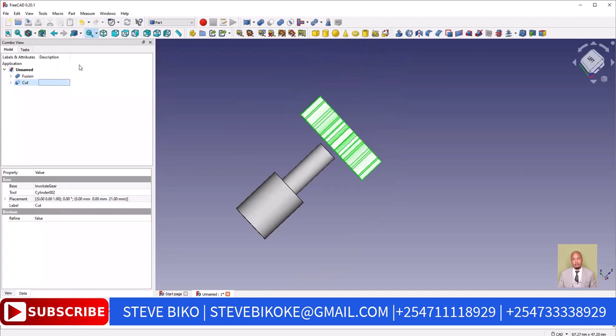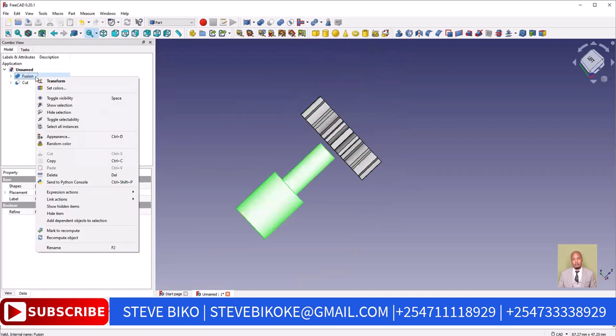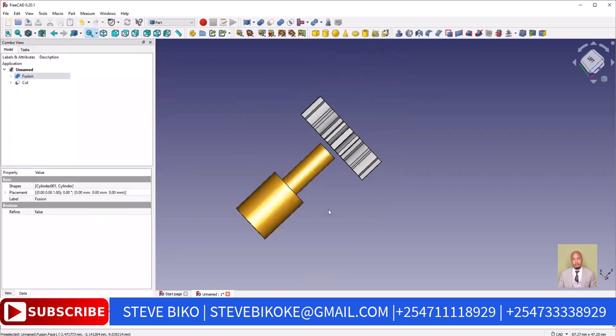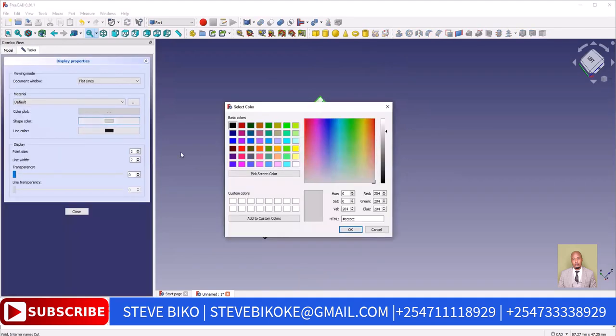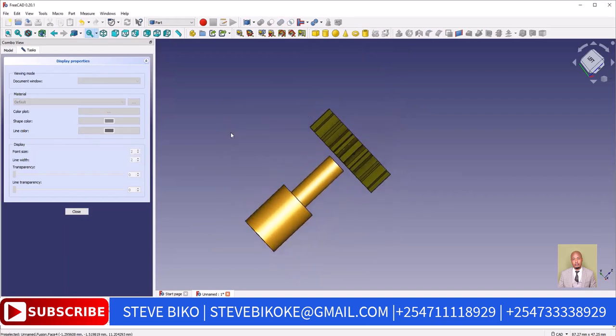Then now we can give them some nice color. So we start with the axle. We right click on the axle. Then we go to appearance. Then I'll choose brass. And there's my color. With the gear wheel, I right click again, appearance, then shape color, I will do that one. Yes. Now we close.